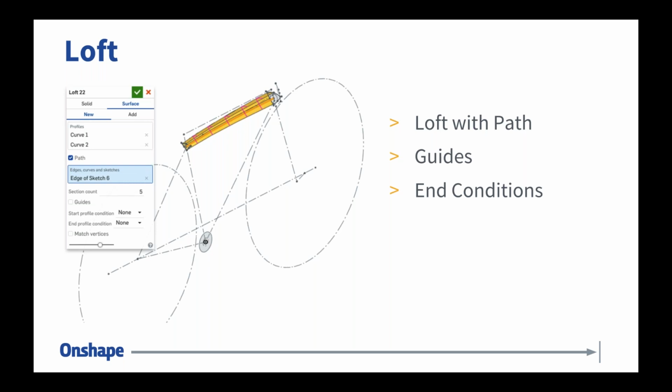So an example I've already given you when we were talking about bridging curve is creating smooth transition between other lofted profiles. In the example I gave you earlier, we created those bridging curves between the seat post and the top post of the bike frame, and I lofted between those edges with the bridging curves as guides to control that shape. That's an excellent example where the loft command is really valuable. We don't have dedicated special functions.